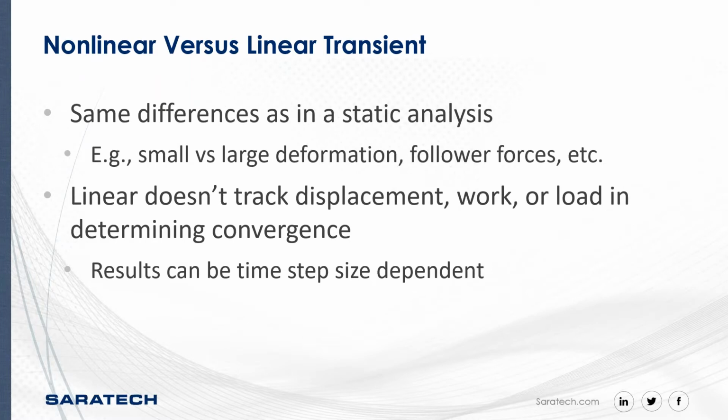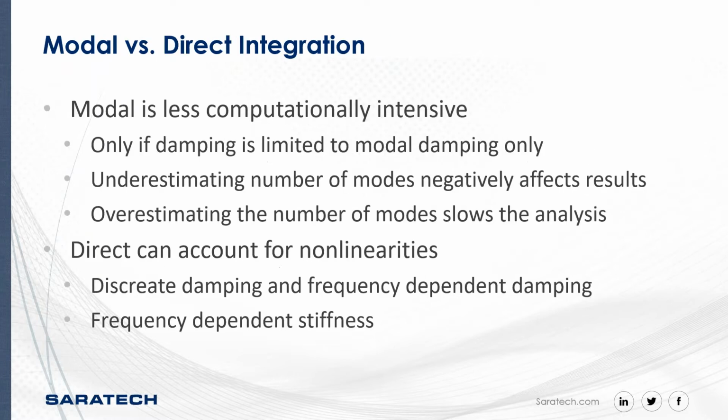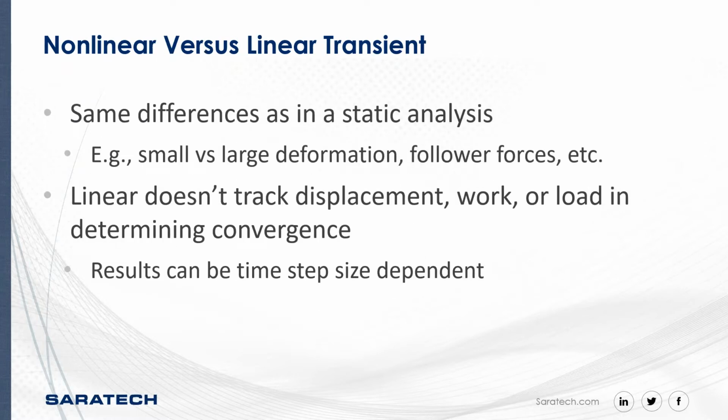There is the nonlinear versus the linear transient. The differences are similar to that of a static analysis. So we've got our small versus large deformation, our follower forces, or even just nonlinear material. We can't use those in the linear analysis, but we can use those in the various nonlinear approaches.